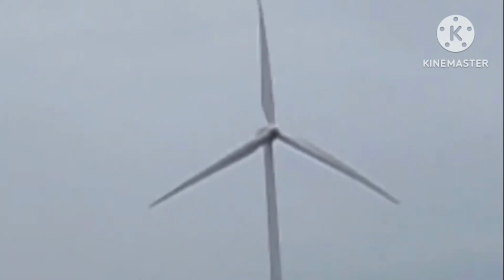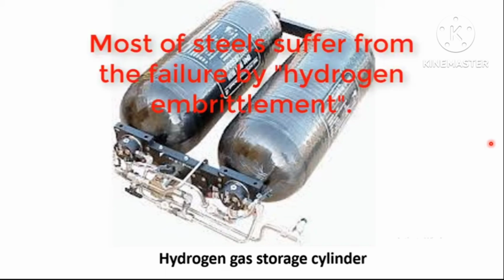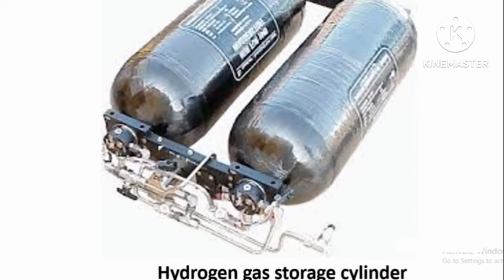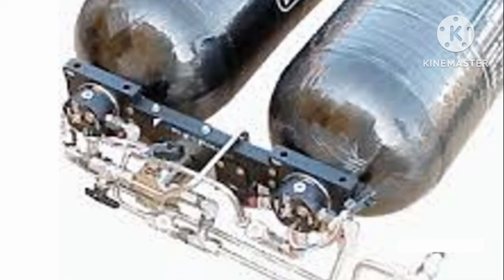The other energy sector that urgently needs FRPs is the hydrogen gas-based energy production. One of the challenges in this field is the storage of H2 gas, which is quite damaging for metals such as steel because of hydrogen embrittlement. Also, for any mobile energy solution such as for automotive application, it is necessary that the storage tank is very light, not a bulky steel cylinder. This is solved by having FRPs as the materials for hydrogen storage tank or cylinders.